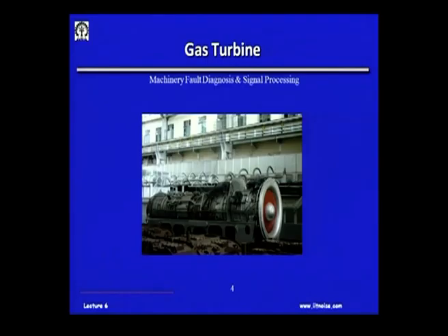Now, this is the case of a gas turbine, wherein this turbine rotates at about 30,000 rpm, and there is a series of such impellers, which will be the compressor and then the turbine. In the compressor there could be many such blades or vanes in the impellers, and if one such set of compressor ring undergoes an unbalance, it is going to give rise to a radial force.